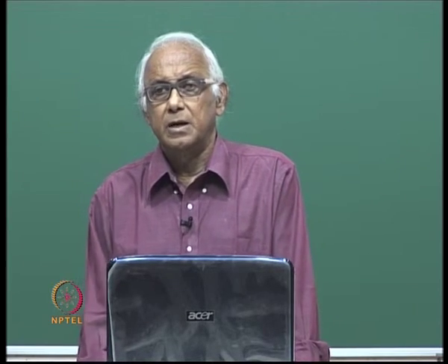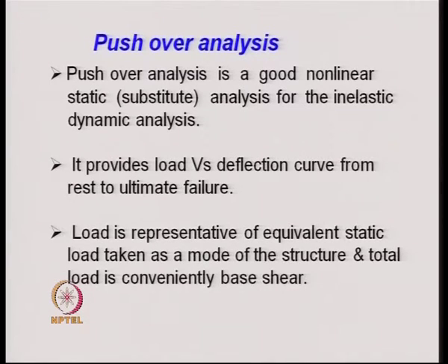The main thing that the pushover analysis provides is a single load deflection curve from zero loading to the ultimate failure state. Load is representative of equivalent static load taken as a mode of the structure, and total load is conveniently taken as the base shear.